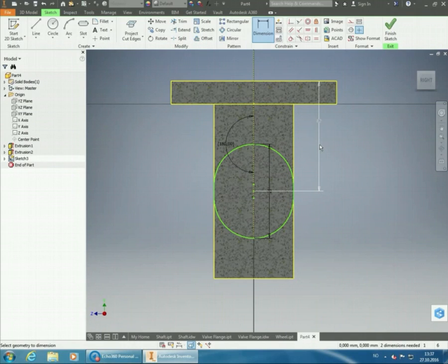You slot with the overall length. Yeah, because then you can set that the overall length of the slot is going to be 70 millimeters. If you use the 2 center points, you just have to set it as 10 millimeters for the length there. 82, I'll move this one so it's easier to read. 82, yeah.